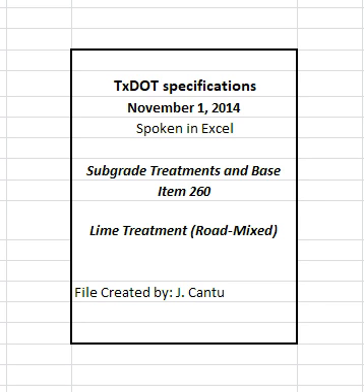5.1.4 Carbide lime slurry. Lime slurry will be measured by the ton, dry weight, as calculated from the minimum % dry solids content of the slurry, multiplied by the weight of the slurry in tons delivered. 5.2 Lime treatment. Lime treatment will be measured by the square yard of surface area. The dimensions for determining the surface area are established by the widths shown on the plans and the lengths measured at placement.